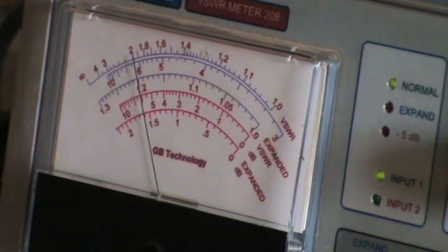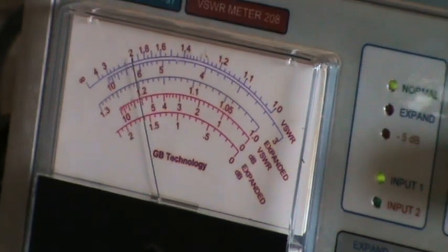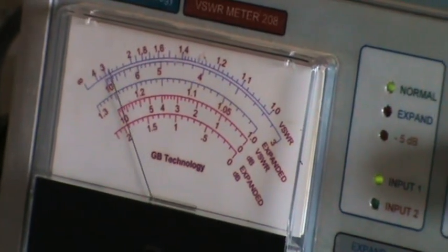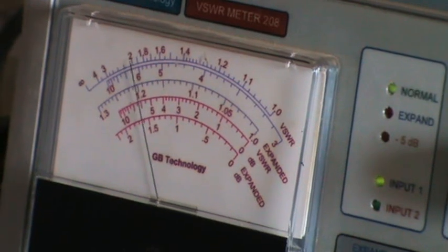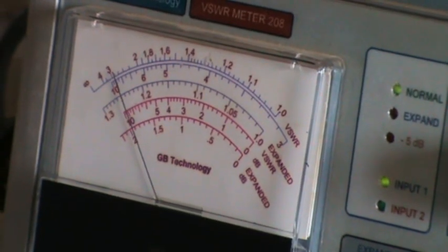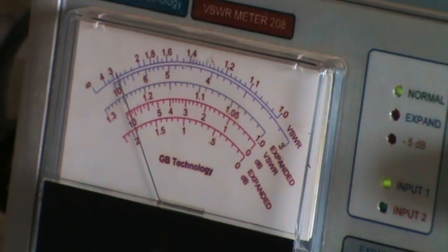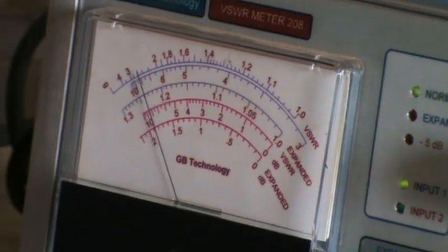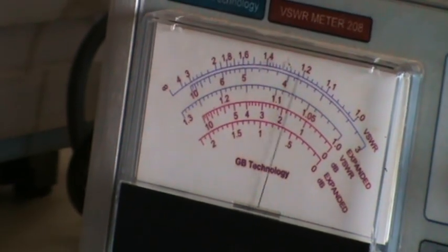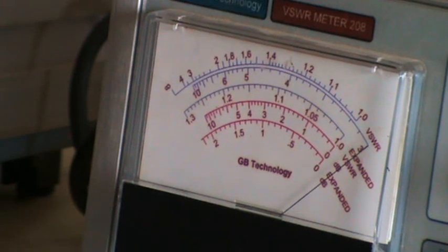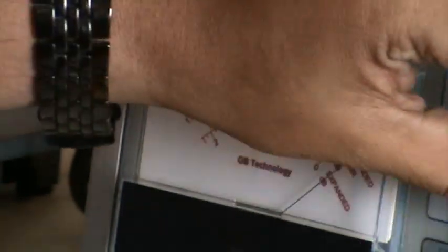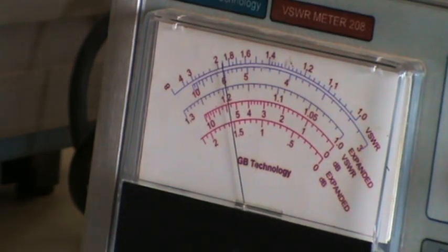68. What you can observe here is, except one frequency, so that is 2.5, at all the other frequencies there is high attenuation happening. At 2.5, the attenuation is minimum. It is around 55. So that means at this frequency there is a resonance happening.